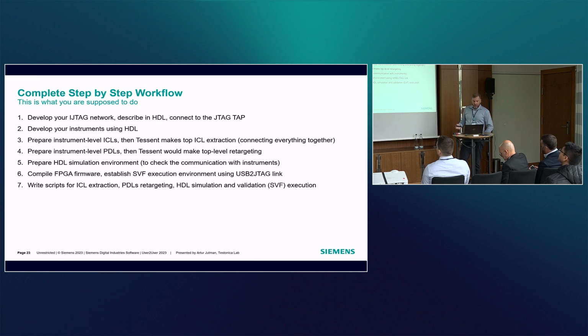You need to develop your instruments using HDL. You need to prepare instrument-level ICL and instrument-level PDLs. Then Tessent would do the top-level ICL extraction, connecting everything together, and would do PDL retargeting for the execution from the SVF executor.